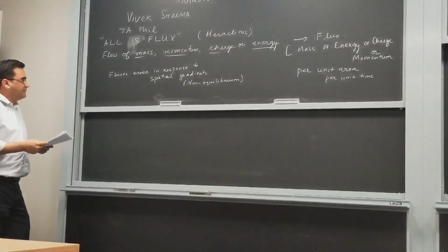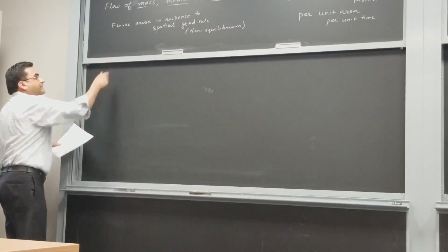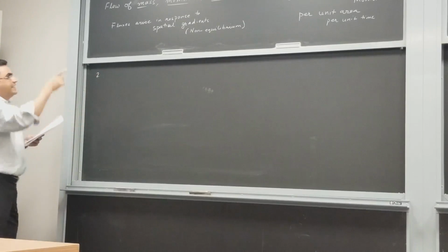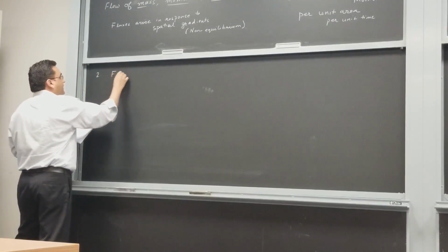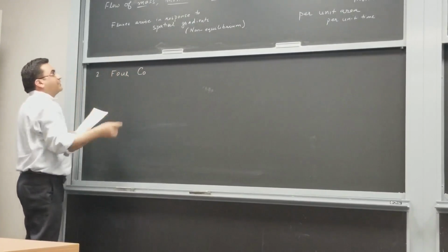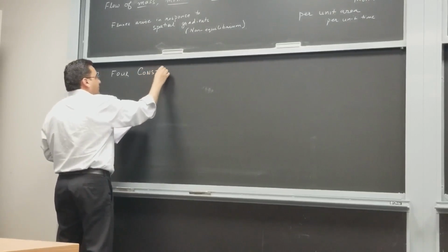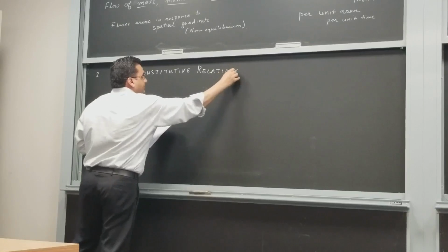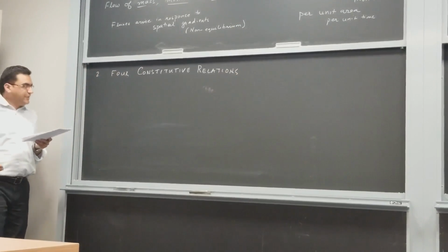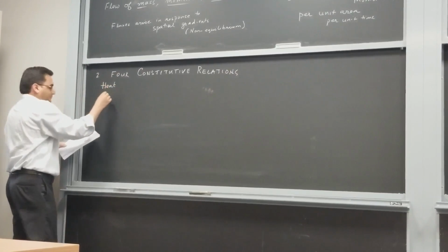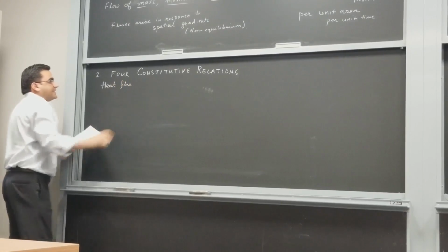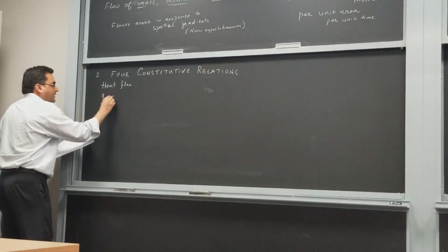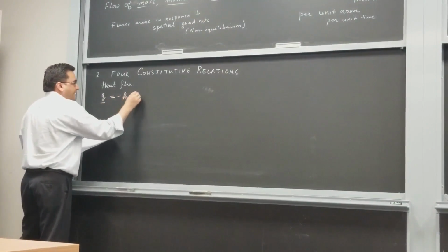And we'll try to define each one of these terms in great detail as we go along, but today we'll start with some very elementary relations that most of you who've taken transport phenomena have seen and probably remember very well. All right, so the first idea is defining flux. The second idea is going to be, for all those four cases that we're going to discuss in this class, there are four constitutive relations. And what these constitutive relations allow you to do is correlate each of these fluxes, heat flux, mass flux, charge flux, momentum flux, to, in case of heat flux, a correlation with temperature gradient.